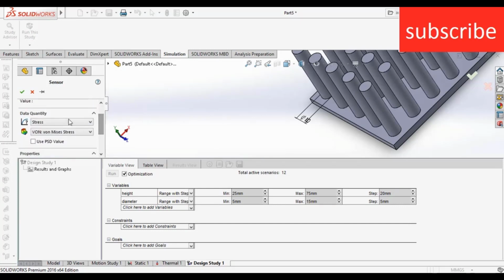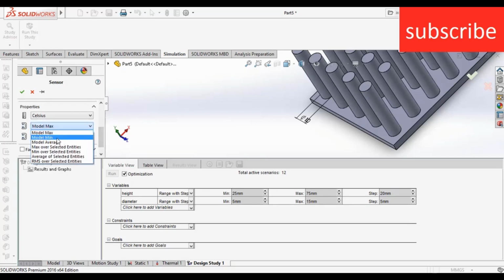Now down below you see lots of data quantities, but stress, strain, displacement are useless in the case of thermal, because what we need here is thermal simulation. So we select thermal. After that select the dimensions, and select the units as per your requirements. Here you see model max, model minimum, etc. You can choose as per your requirement.